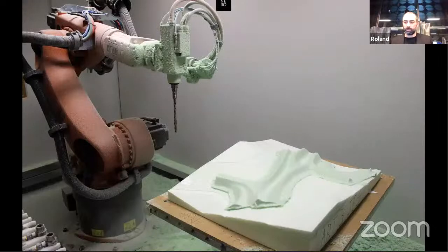Those were milled from foam in quite a traditional way. So this is using robotic 5-axis milling. And it was quite a tedious process. We had to mill a jig, then we had to mill the back side of the part, then we had to mill the front side of the part. And I guess by doing this process, we began to realize that this has certain limitations. This is a process which, although undertaken by a machine, is incredibly machine intensive. It used a lot of robot time.